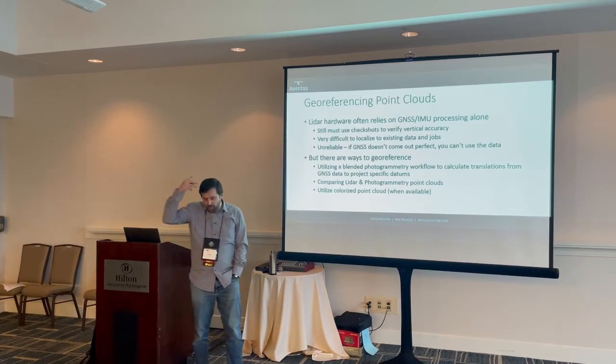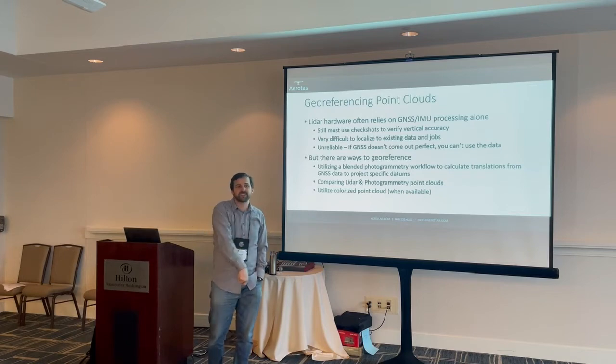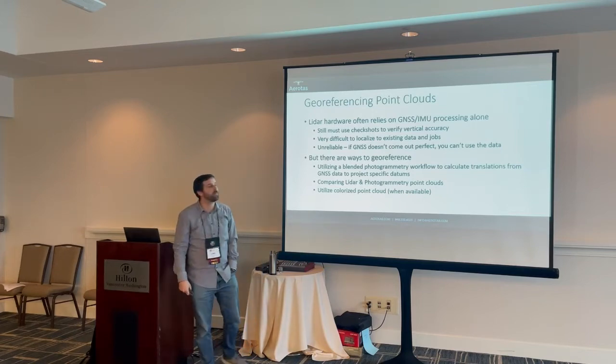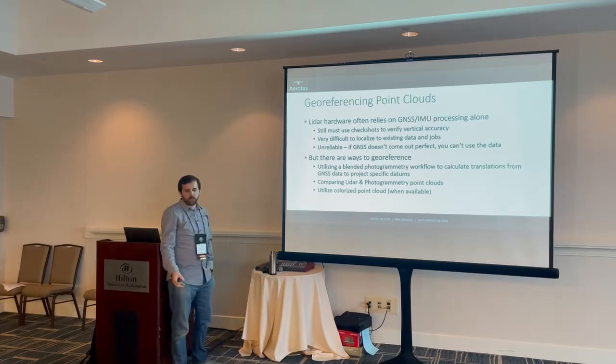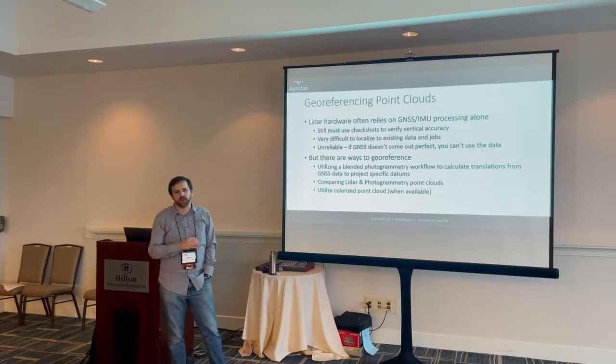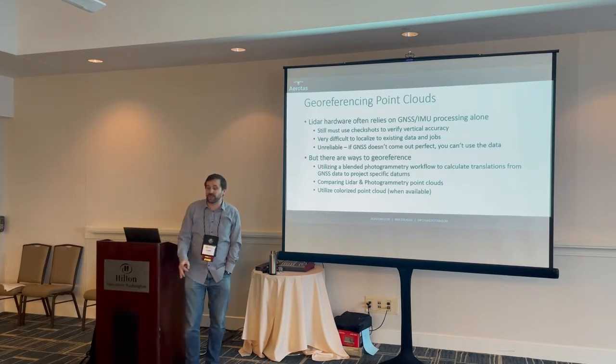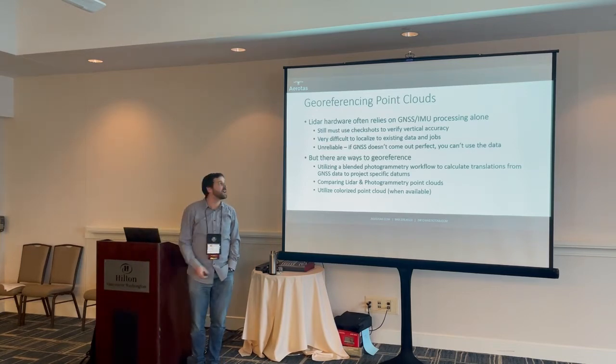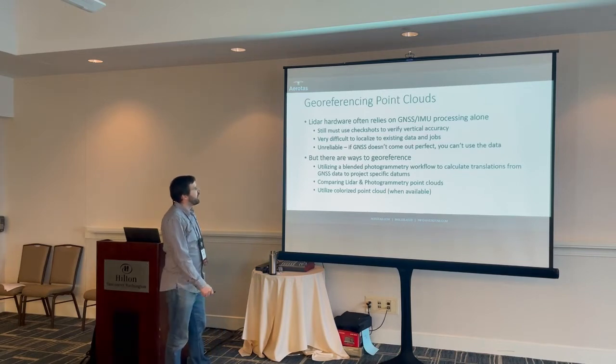That drone is moving at 30 feet per second, and it is not stopping, and you can't go back and measure the same point. So that's part of why I really don't like a lot of the hardware people that say you can operate drone hardware without any ground control points, because if nothing else, you just want to verify that something didn't go wrong, because sometimes things go wrong.